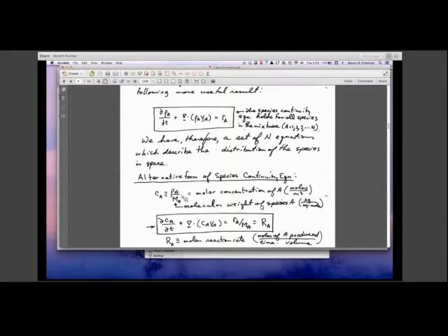we've done a number of problems so far working in molar coordinates, not mass coordinates. And so how do we convert this from mass to molar coordinates? That's what I'd like to talk about next. And I would assert that probably the best way to do it is to start from the result that we just derived, rather than restarting over with the material volume and the fundamental postulate of conservation of mass and reapplying the transport theorem again,